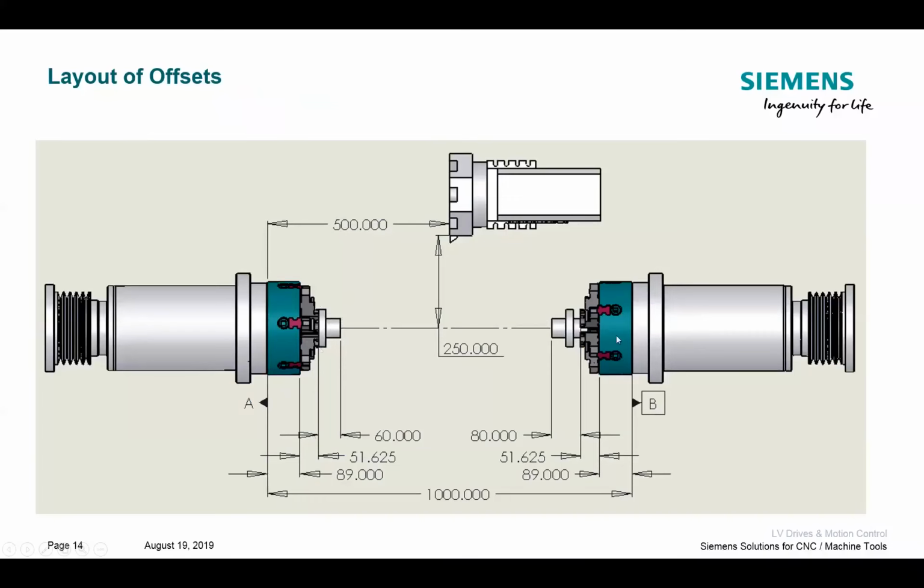Then I'm going to think about how I want that part to sit in the second spindle once I've done the transfer. Once I come over, I have to make sure that I pull it back in a known location, or my zero may be in a completely different spot. So there's a couple things that I really need to pay attention to. Where am I sending the Z2 when it's done? But additionally, how much did I throat the part by? All of this can affect where the second work offset is, because I'm going to have 2 work offsets when I'm all said and done. I'm going to have a G54 most likely, and then in this case I'm going to use G55 as my secondary work offset. And I need to know where that's going to fall in space.